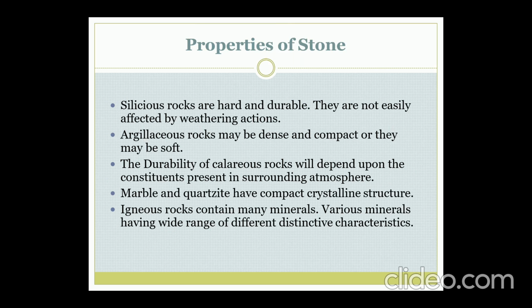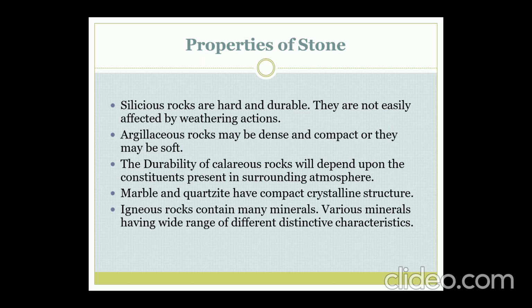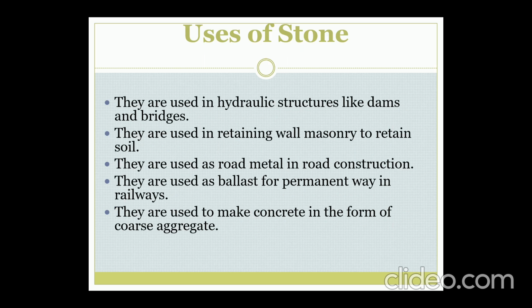The properties of the stones: siliceous rocks are hard and durable. They are not easily affected by weathering actions. Argillaceous rocks may be compact or they may be soft. The durability of calcareous rocks depends on the constituents present in the surrounding atmosphere. Then marbles and quartzite have compact crystalline structures. And igneous rocks contain various minerals having a wide range of distinct characteristics. So all of these are the properties of the stones extensively used in the construction field, and these are the uses of the stones.